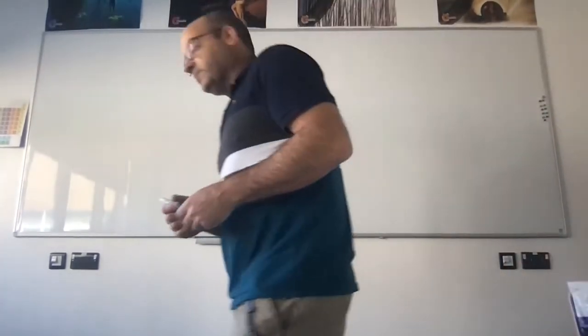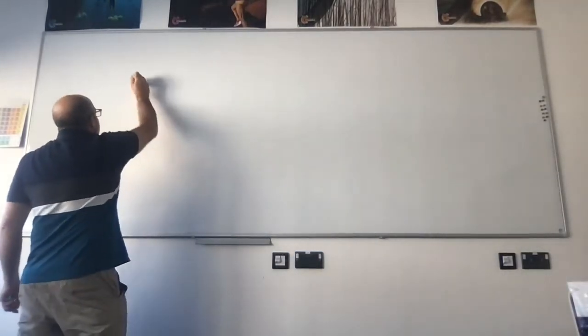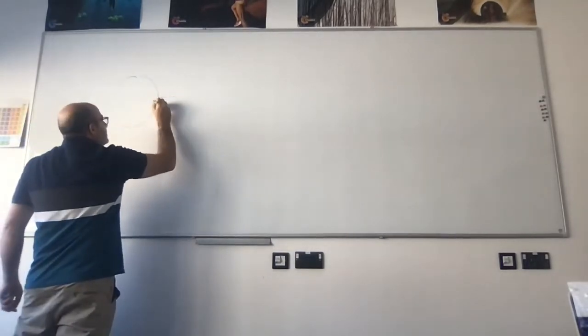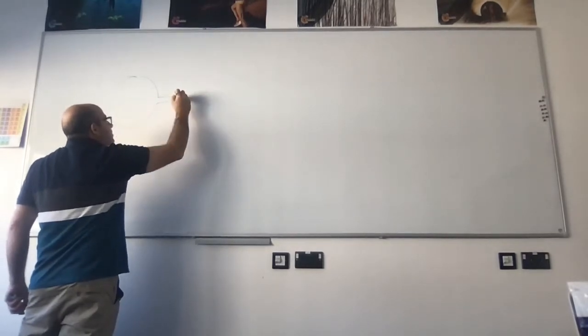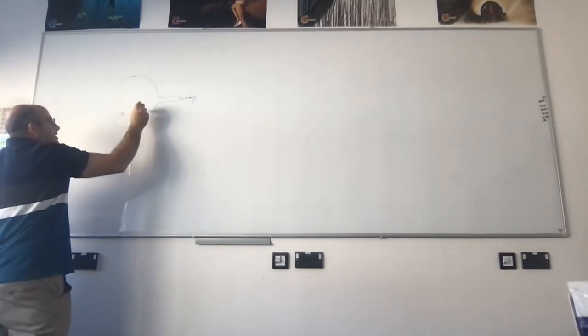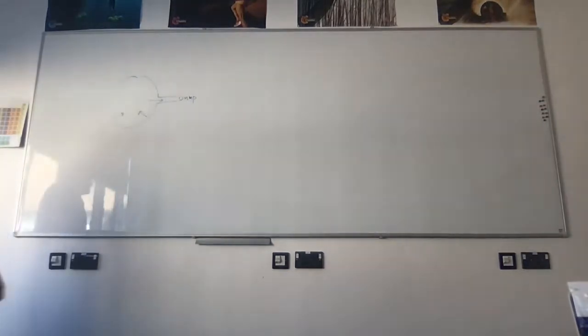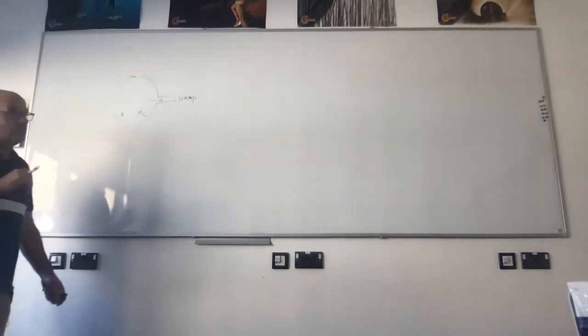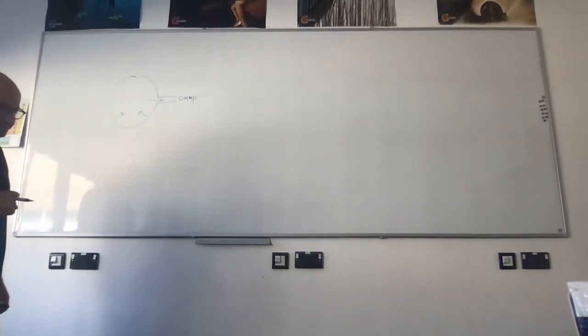Okay, so a quick reminder of the point where we stopped last time. Last time we were looking at this schematic diagram. You don't have to draw it because you should have it in your notes, where we had some pump, and we were looking at various processes which were producing gas, as opposed to the only process which is extracting the gas, which is the pump. The idea was to try to understand how vacuum is achieved, and this is going to lead us today to start talking about different types of pumps which you might encounter in the lab, and how they work.